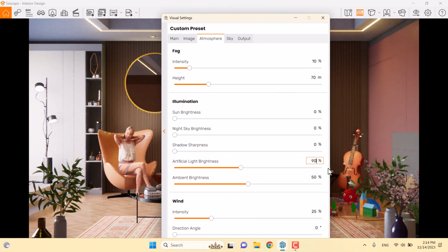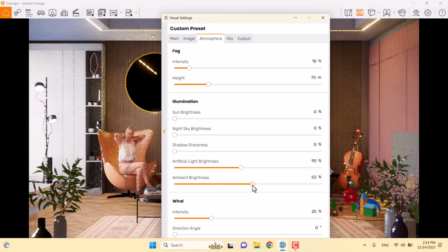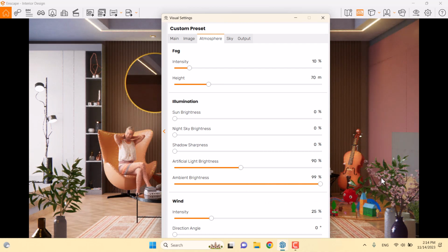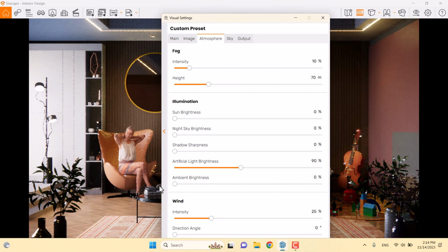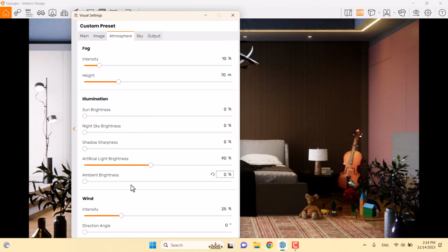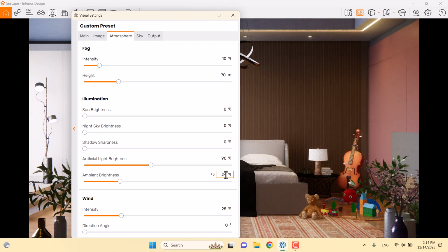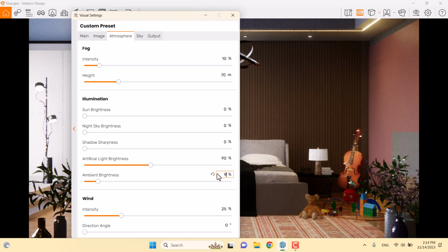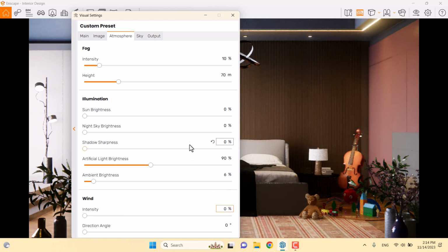Ambient brightness related to the interior rendering and lighting. It can automatically help you to create some better lighting for interior with exterior lighting. And when I decrease it, you can see some type of more darkness in your job. For now, I prefer to use some low value number, about 24% or maybe 9%, because the value of it really works exactly with the GI light. Wind is 0 and fog is 0.